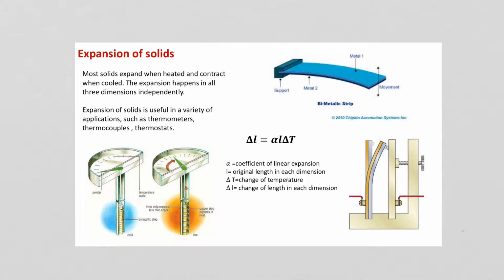And so this can be used for thermometers, like this cooking thermometer, where the strip is wrapped around a post which is connected to a gauge needle, and so depending on whether the strip is going to expand or contract, the gauge will move, and one would be able to read the temperature that the thermometer measures.